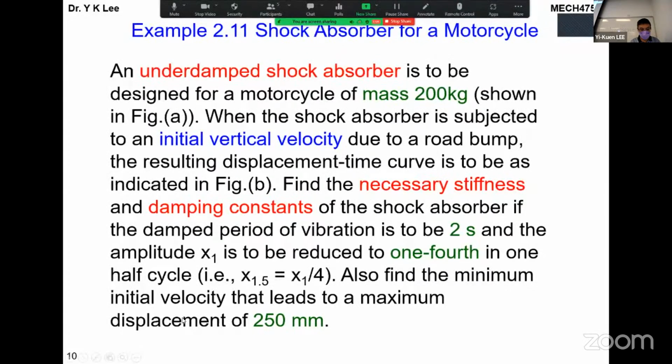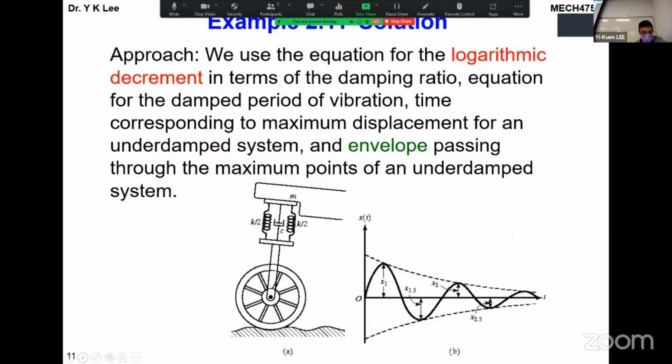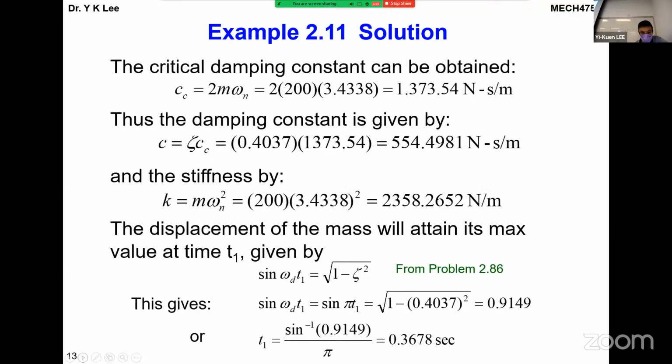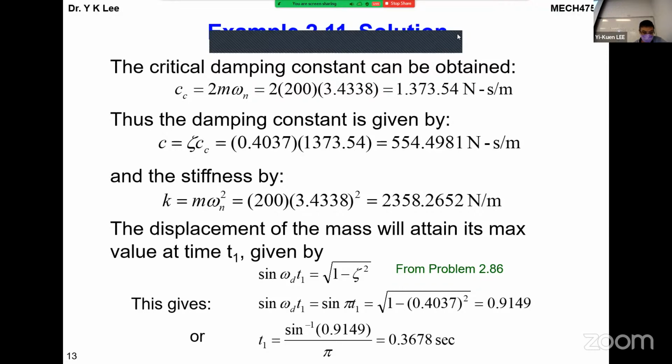Anyway, I will skip this part. This time we mention it as an exercise. Of course, if you assume a one degree of freedom model, then we can use vibration data from a motion sensor. It measures the vibration as a function of time, and then we determine the damping ratio, the normalized damping coefficient. In that case we can determine the maximum vibration amplitude. That is an important thing we discuss this time.